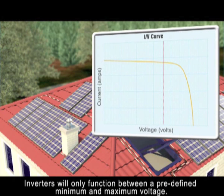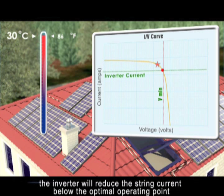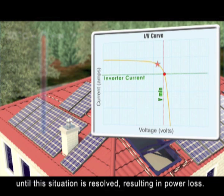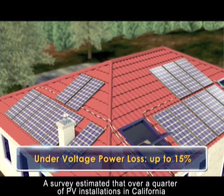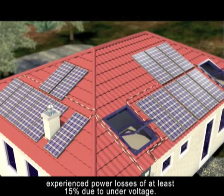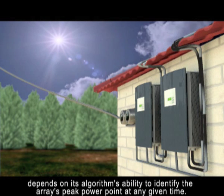Inverters will only function between a predefined minimum and maximum voltage. If the solar array produces too little voltage, for example, due to high temperature and short strings, the inverter will reduce the string current below the optimal operating point until this situation is resolved, resulting in power loss. Undervoltage is unavoidable in many cases where short strings are required. A survey estimated that over a quarter of PV installations in California experienced power losses of at least 15% due to undervoltage.